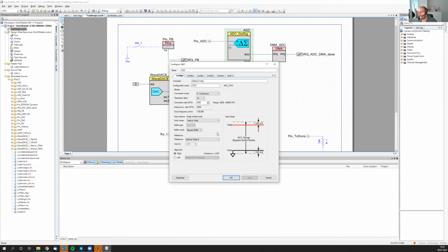But my recommendation here is to simply leave it as it is, and we have to deal with a certain error. And then you can simply write in your report, my amplification maybe is a little bit off because our reference voltage for the ADC had an error. So no need to over-engineer that.